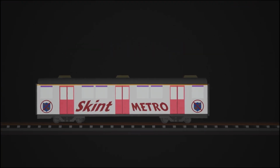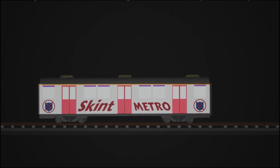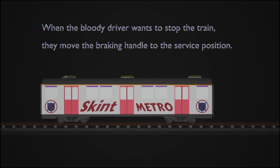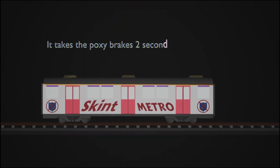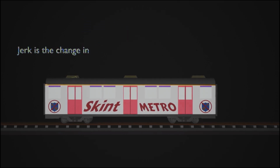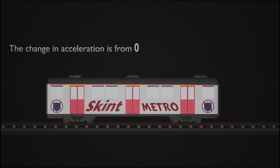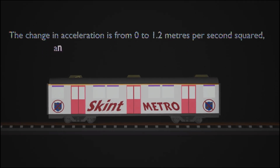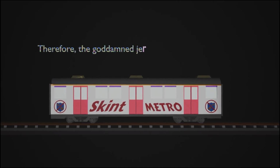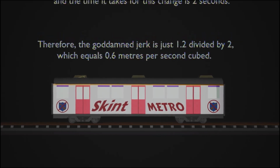Jerk example. A metro has a braking rate of 1.2 meters per second squared. When the driver wants to stop the train, they move the braking handle to the service position. It takes the brakes 2 seconds to fully engage. What is the jerk? Jerk is the change in acceleration divided by the change in time. The change in acceleration is from 0 to 1.2 meters per second squared, and the time it takes for this change is 2 seconds. Therefore, the jerk is just 1.2 divided by 2, which equals 0.6 meters per second cubed. So there.